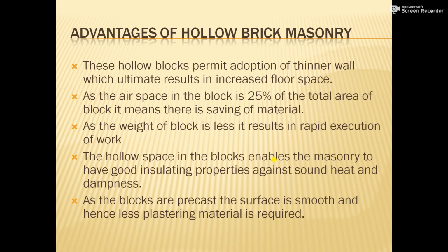Now we can see the advantages of hollow brick masonry. First, this hollow brick permits adoption of thinner walls, which ultimately results in increased floor space. As we are providing cement concrete blocks, these blocks have greater strength compared to bricks and stones, and because of that the size can be reduced, and we get increased floor space in the masonry.